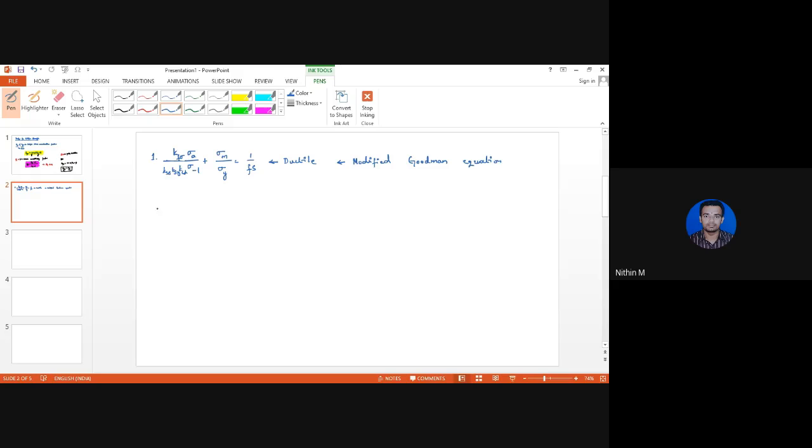So remember this. Next, if we encounter brittle materials, in a similar fashion we will make use of the Goodman criterion, where the only difference is that sigma y is replaced by sigma u. So this is Kf sigma multiplied by the stress amplitude, divided by KSR, KSZ or KLD multiplied by the endurance limit of the material, plus sigma m by sigma u, is equal to 1 by factor of safety.